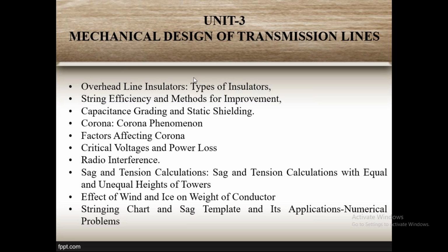If the insulator fails, you will definitely get the shock. Similarly, in your house, if you touch a wall, you may get shocked. That is because of insulation failure. If the insulator fails, then the current will pass everywhere. That is the importance of the insulator in the transmission line system. Next one is string efficiency and methods of improvement. What is the importance of string efficiency? Suppose you are connecting the conductor between two transmission towers through the insulator.